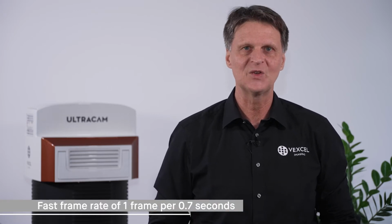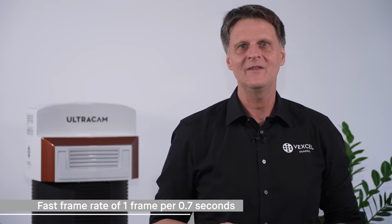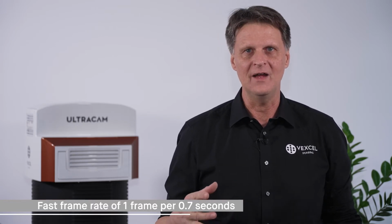Another common feature of the fourth camera generation, thanks to the CMOS technology, is a much faster frame rate. So we are now at 0.7 seconds frame rate, and that enables to either fly faster, or to collect imagery with a higher forward overlap, or do a mixture of both. Across all cameras, the footprint increased across the flight strip as well as along the flight strip.